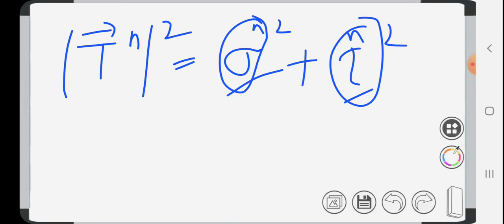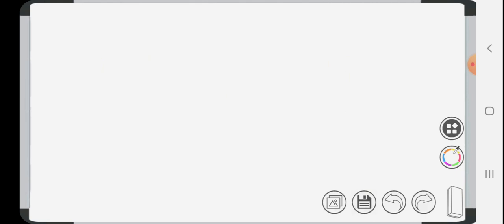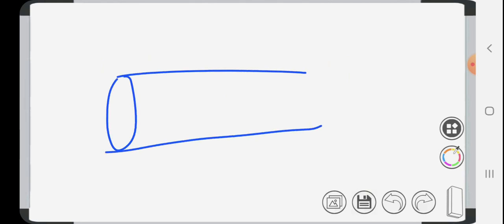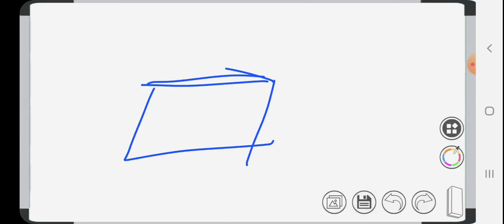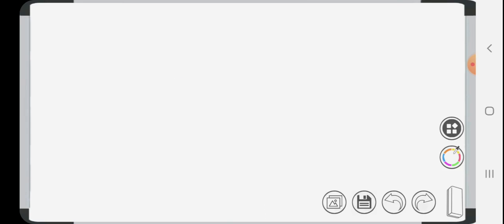So these ideas you have already learned in previous sessions, right? Because in the case of perpendicular loading, we have studied that we will have normal stress. In this kind of force we will have shear stress, right? So that is how we learned with a simple geometry and simple loading. But in complex loading, this is how we define normal and shear stress components.